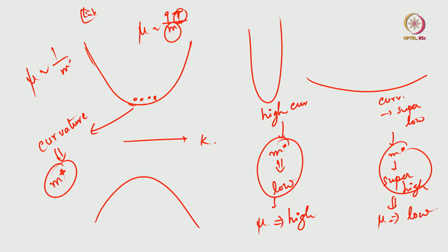Not talking about holes here, because microwave devices are predominantly unipolar, in the sense that we use predominantly electrons to transport, especially in III-V materials like gallium arsenide, MESFET, HEMT, etc. We do not have hole transport as an active layer, so we are talking about electrons here.